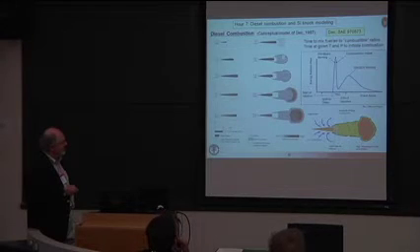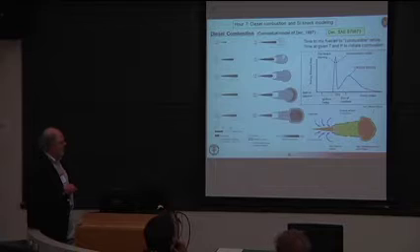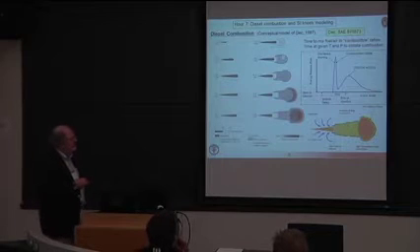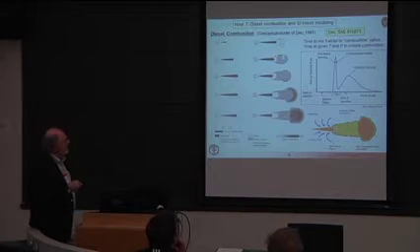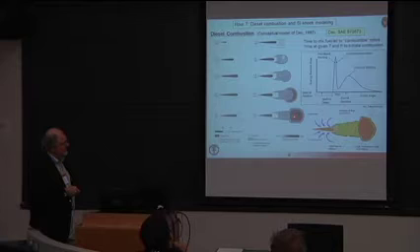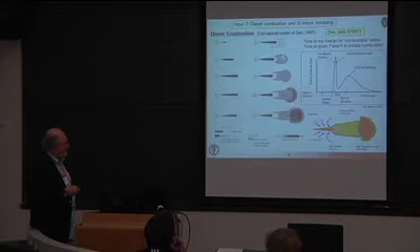The vapor continues to penetrate. And you start to see the development of, he calls them PAHs here, but precursors. And then a flame is established. This thin line you see here is a diffusion flame. And then eventually soot starts to be produced, starting from those precursor species like we discussed last time.